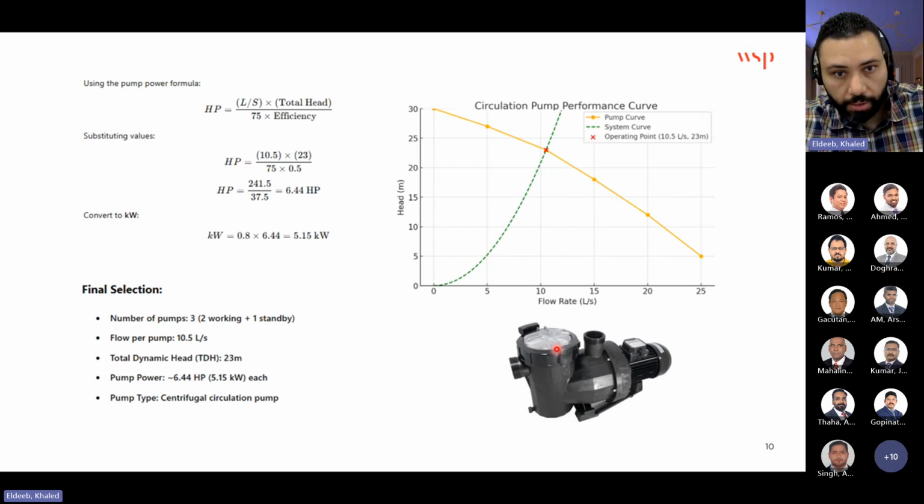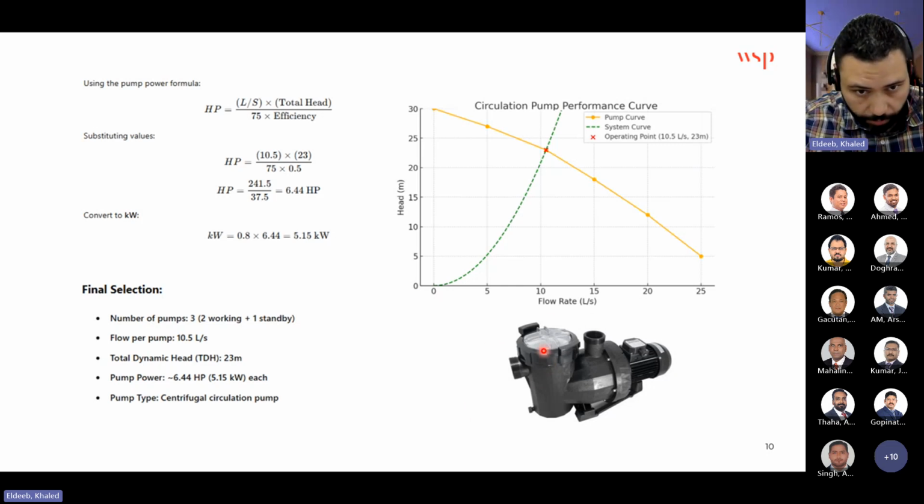You see here in this pump we have a strainer. Okay, so we need to remember those points. A swimming pool pump should be a self-priming pump. It should maintain a velocity of 1.5 meter per second at the suction, and we will discuss this in detail when we go to the part of how to calculate the pipe size. And then the delivery could be slightly more, reaching 2 meter per second. If you remember in the chart example that I showed you just now, I considered 5 feet per second, which is equivalent to 1.5 meter per second. This one is on the suction side.